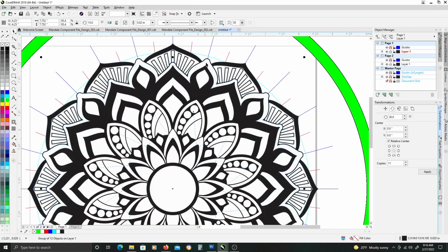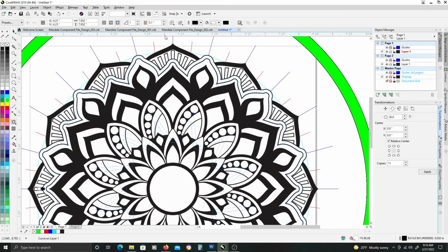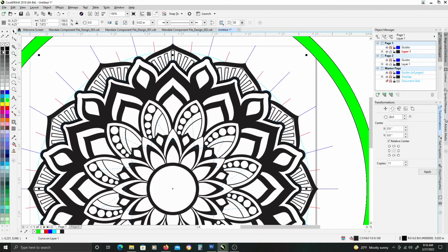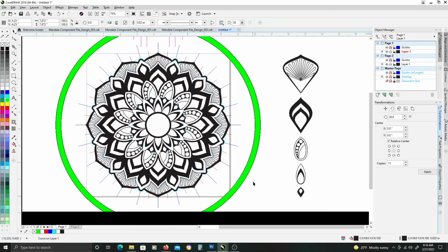And the last thing I want to do is create a connecting black outline object. So with this outline object selected, grab the contour tool again. We're going to duplicate, we're going to lessen the size, hit Control K, select the object, give it a black fill, and then shift page down, and there.